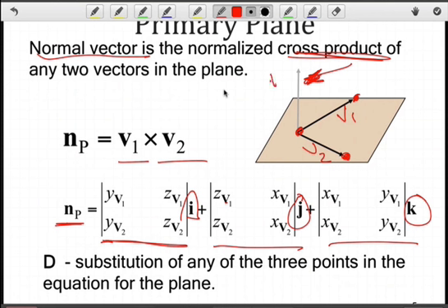If I calculate that with actual values for the points, now I've got this vector corresponding to the normal to the plane. And then to solve for D in our original equation, ax plus by plus cz plus d equals 0, all I have to do is select one of the 3 points and substitute it into the equation and solve for D. So now I have my primary plane. Also note that it's completely unrestricted. Because it is the primary datum, there's no influence from any other features in terms of establishing that datum reference.